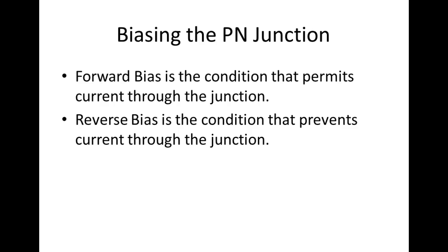If you put a voltage potential across something, and there is a path through it, and it does not have infinite resistance, then there will be current flow. It's just that the current flow through the insulator is so small we can't even think about measuring it, down in the picoamps.